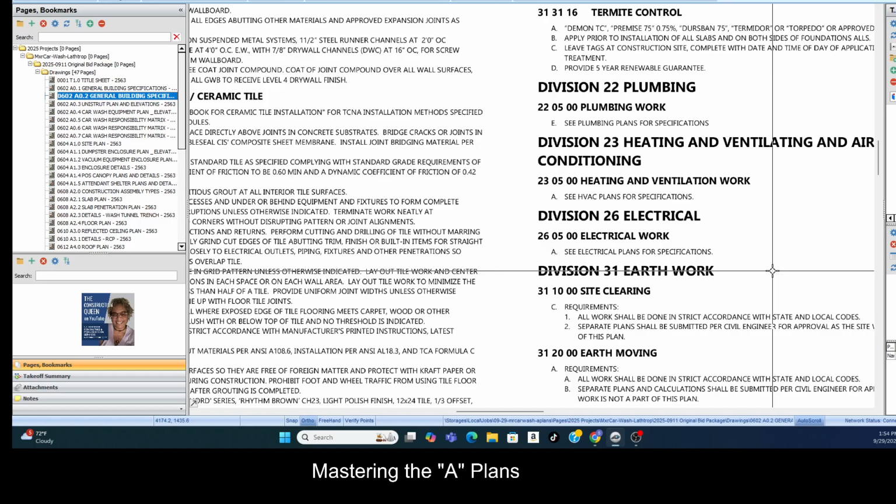Also in the architectural set is demolition. So if it's a tenant improvement, you will find D plans, AD, you'll see. Architectural demolition. That's where you'll find your demo. Now, you may have demo also if it's new construction, you may also have demo in your civil set because, yeah, you may be getting rid of some, the building's been knocked down, but the parking lot's still there or something, so you may have to demo all of the concrete or asphalt or the pavement or whatever. So you want to make sure, demo, all your stuff is in the architectural set.